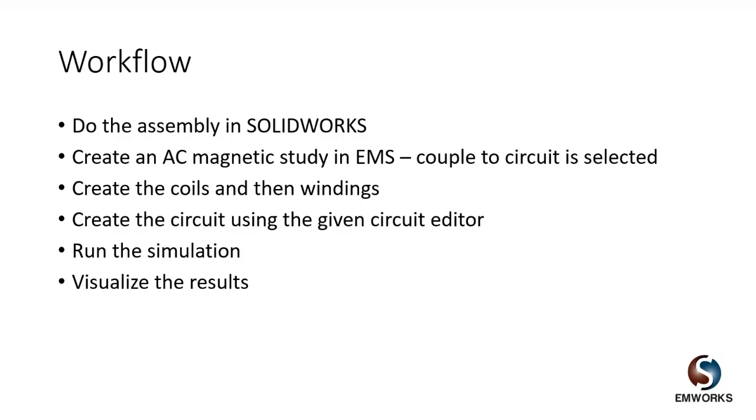And then we will couple that to a circuit. While creating an AC magnetic study, one needs to input the frequency, and we will do that. Then we will create coils and then windings, and then we will use the circuit editor to actually assemble the circuit using the windings created in EMS. Once the problem has been defined, we can run the simulation and visualize the results.